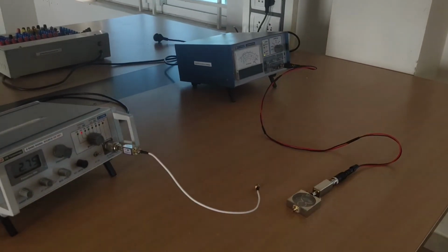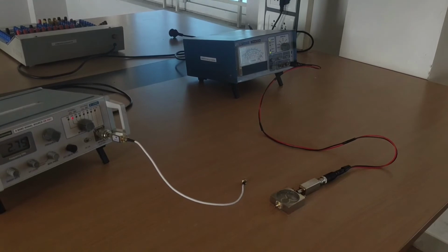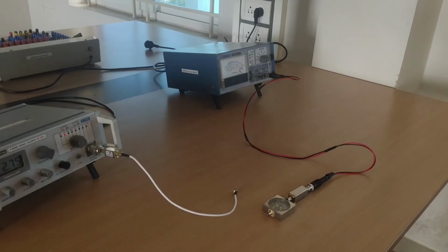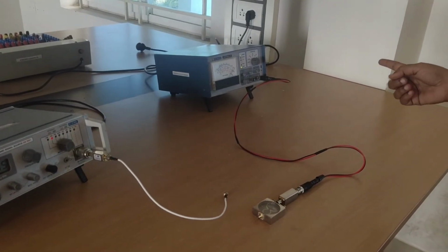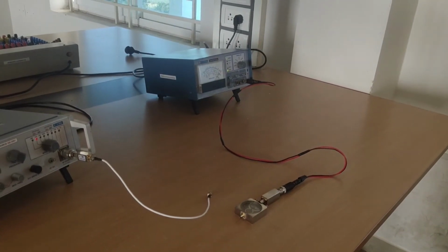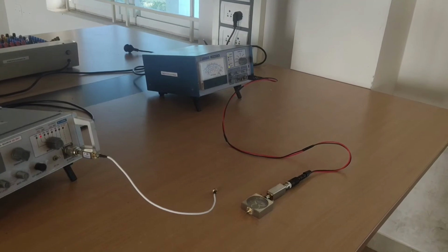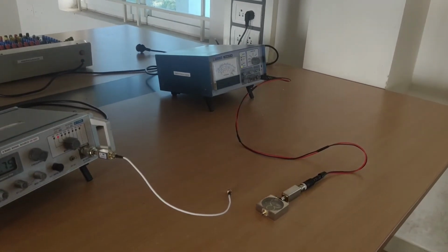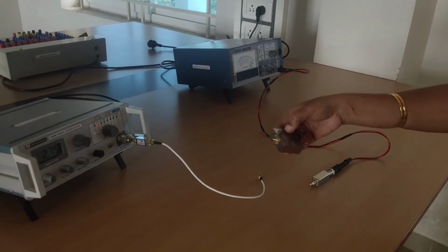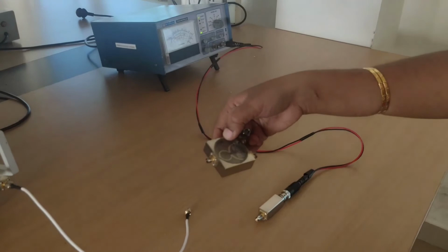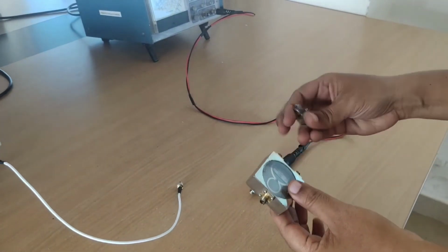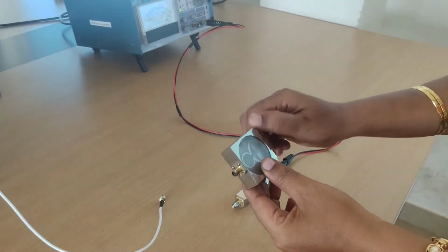Let us see the demo of power division and isolation of the microstrip power divider. So here again we need a microwave signal source with the modulation attenuator pad, VSWR meter, transmitting antenna and receiving antenna. Here the source signal will be from 2 to 3 GHz, an attenuator of 3 dB, and a VSWR meter with a detector. This is the power divider. In this power divider, we are going to calculate the isolation or the loss in the power. So again we are using a 50 ohm matched load.